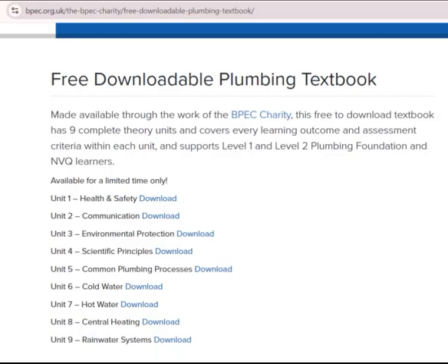AC 6.4 Identify the requirements for earthing of electrical circuits. Electricity will always take the least line of resistance to earth, even if that line is us. If we accidentally touch an electricity source, the current will always flow through our bodies to get to the earth, causing a dangerous, sometimes fatal, electric shock. The reason for this is simple: electricity always wants to complete the circuit. The need, then, for a good earthing system is of utmost importance.